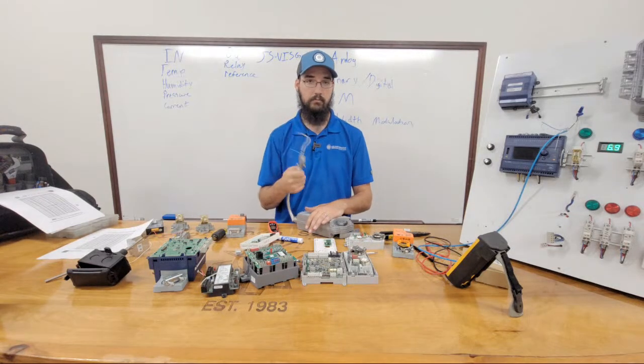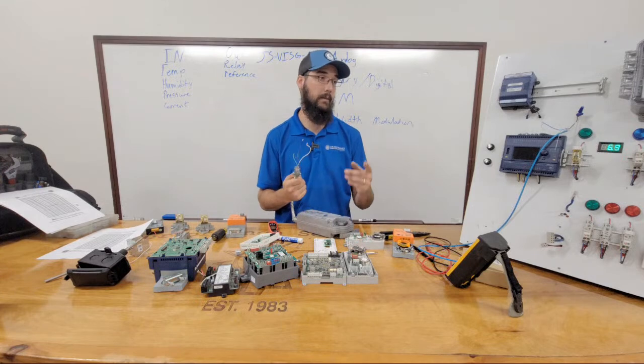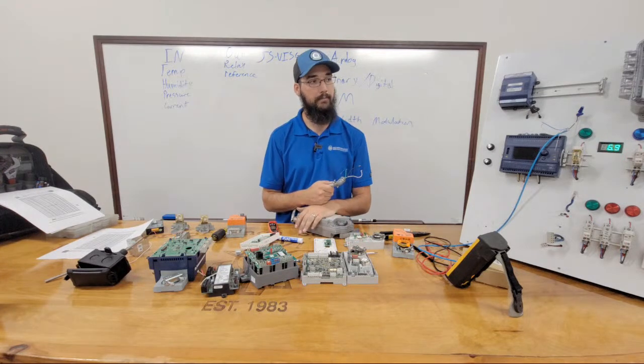And when we're done, we just drop out the coil voltage and it closes. We don't need anything else. And all we needed at that point was one binary output.